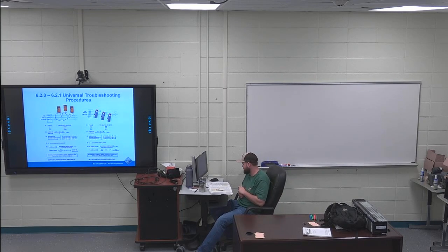They go through how to check fuses and circuit breakers. You did this day one of the electrical motor trainer. I'm not going to go through this too much. Nothing highlighted in 622, fuse checks, circuit breaker checks. First sentence on page 51 is highlighted. The measured line and load voltages should be the same if the breaker contacts are closed. So you're just making sure that a circuit breaker is working by seeing if the voltages on both sides are the same. If they're the same, then it's closed and working.